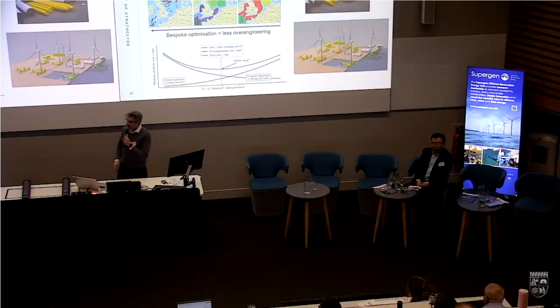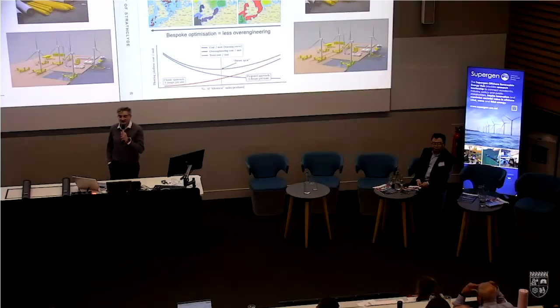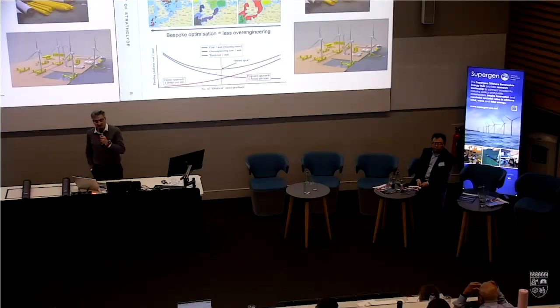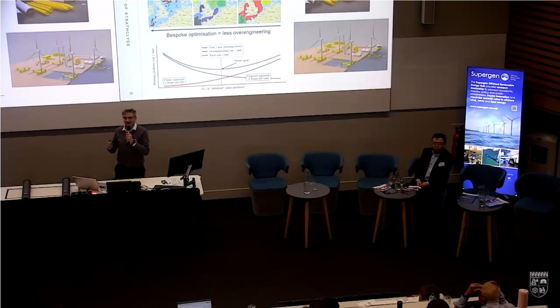So again, it's mimicking what happens for wind turbine generators. In the graph at the bottom left, you may say, if you design for an area rather than a specific farm, you're probably going to over-engineer because you need to cope with all the worst conditions in a large area and not the wind farm itself. That is true. On one side, you augment over-engineering and costs, but on the other side, there is the potential to produce, rather than 30, 40, 50 superstructures, 300, 400.